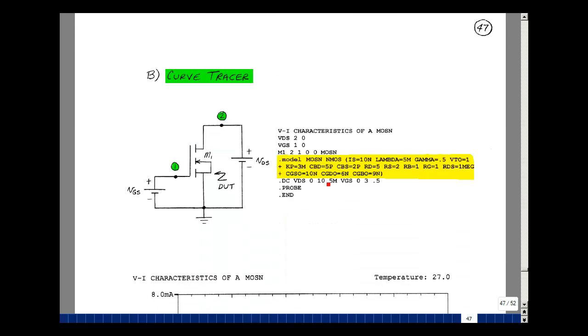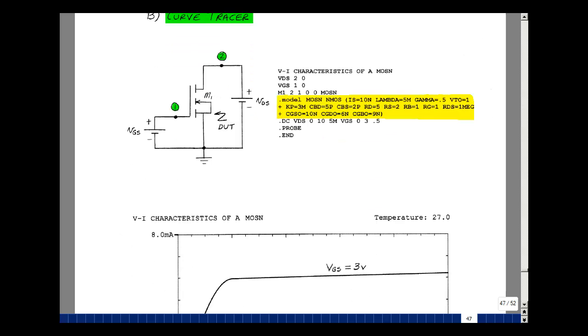I took some typical values for an NMOS transistor with a level 1 model and put the values here. I thought I'd go back and get the curve tracer module from chapter 4, and let's run the curve tracer on this transistor to see what it looks like now that we've added a term lambda, which will act like an increase in slope as we increase the voltage or the current. These are of course static or DC curves, so the capacitances don't show up.